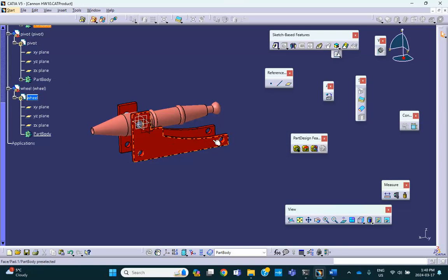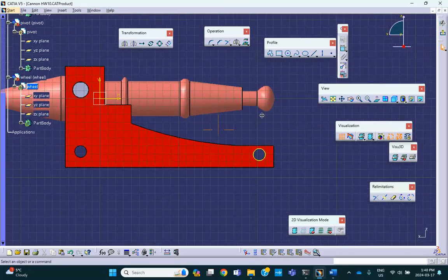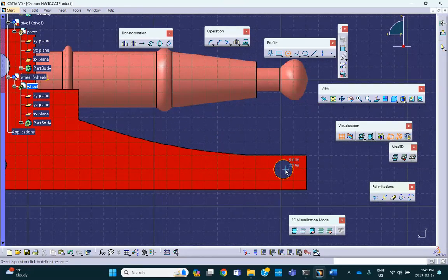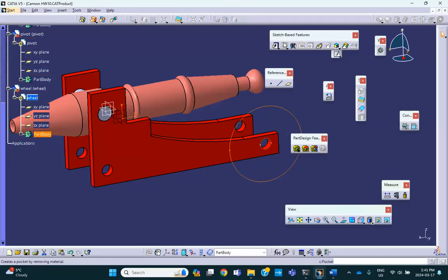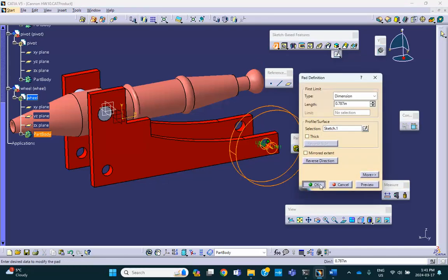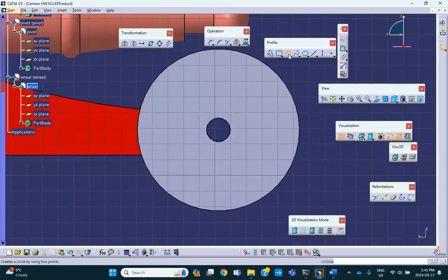On a convenient plane, on that same plane that I had here, on that same frame front face, we'll sketch. Why don't I project that circle? Okay, and do the rest now. So exit, add it, that's fine. And on it, I will sketch. You see what I'm about to do. I'll draw a circle here, which is concentric with these two other circles. Control, that, concentric.